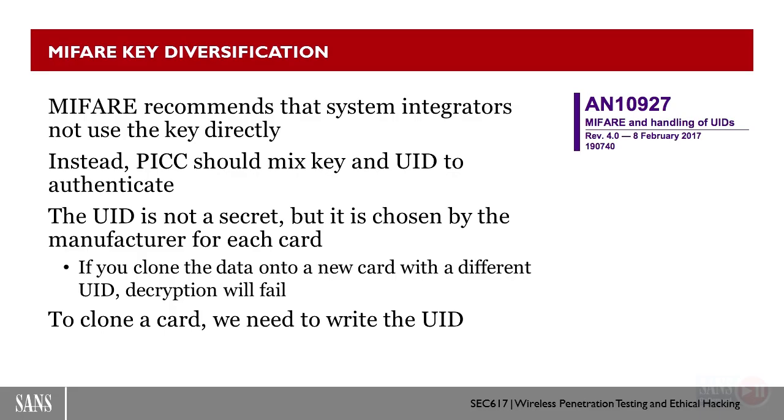The MIFARE standard recommends that we have some key diversification in that we should be using the UID from the card as input into the encryption-decryption function with Crypto1. And not everybody does that.